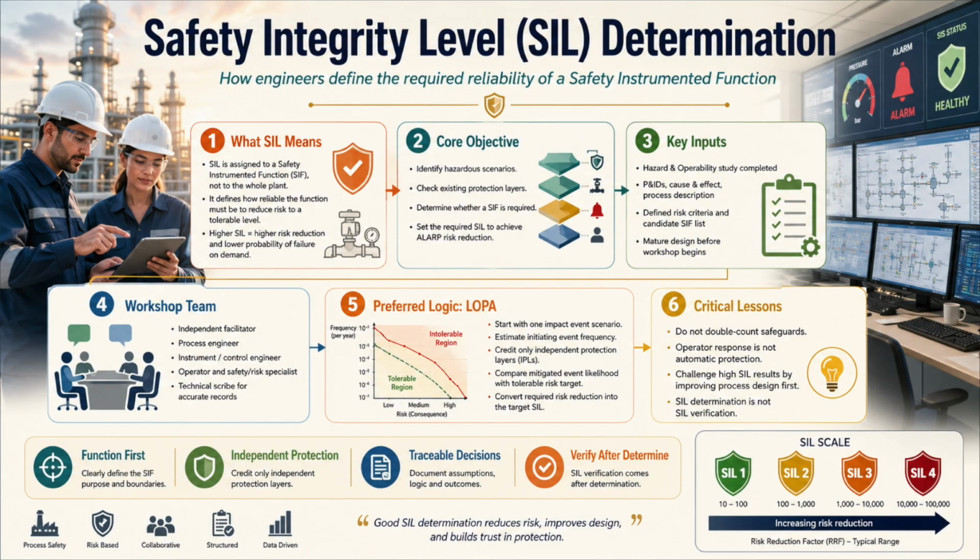A qualitative method may be suitable for initial screening, but higher integrity requirements demand more rigorous analysis. When a matrix or risk graph produces a high integrity requirement, the scenario should generally be examined using a more transparent semi-quantitative method, such as layer of protection analysis.